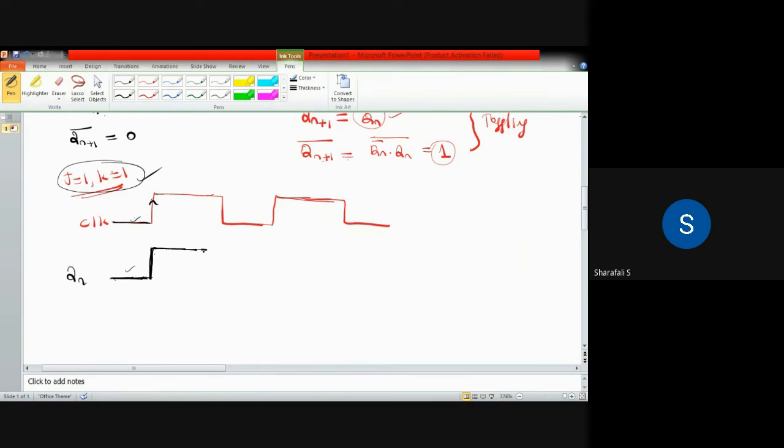And when the next clock pulse comes, which means when the flip flop is active next, while the clock is at 0, the flip flop is inactive and the output state is the same, Qn equal to 1. Then, when the next clock pulse comes, because the present state is 1, it will go to 0 because of the toggling action.